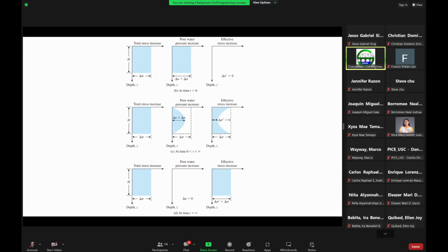So that's why when we do ground improvement, for example, in the case of clay layers, normally we allow the clay to consolidate by about say around 90% degree of consolidation before we put the structure. Otherwise, the structure will encounter very large consolidation settlements.